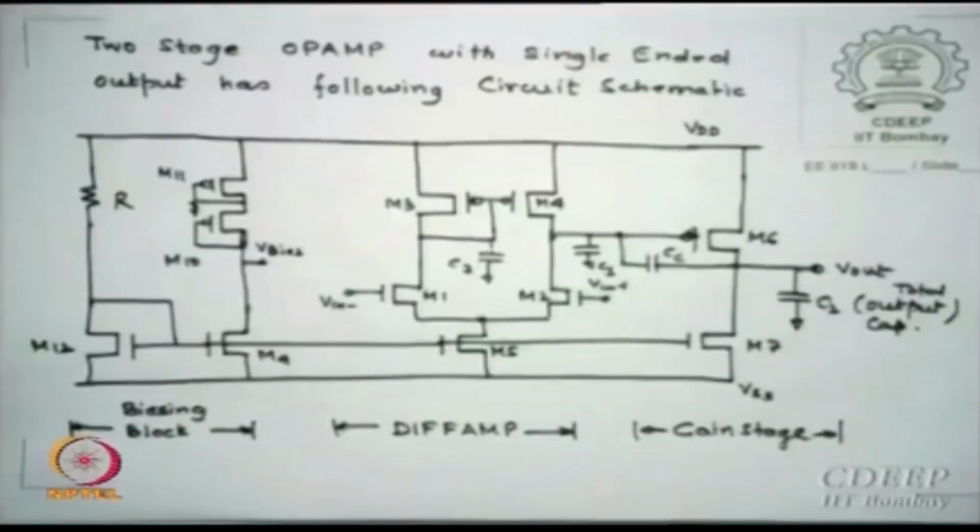Okay, so is that clear to you? I will not right now design for you the value of M10, M11, M9, M12. This can be independently handled as a bias circuit, and in our OPAMP design, to first extent, we will not design the mirror part, because we can anyway independently design it. This has nothing to do with the OPAMP, so that can be independently designed. But just to show you how much circuitry is essentially in an OPAMP is connected there.